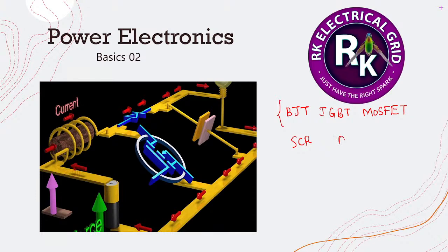There we saw one topic called DC transient. In DC transient, we deal with the transient effect of inductor and capacitor. We saw how they behave with a DC source the moment they are instantly connected to the DC supply, or suddenly disconnected from it. So we have done a variety of things. When an inductor is suddenly connected to the DC supply, what will happen inside the inductor? Same thing we saw for the capacitor also.